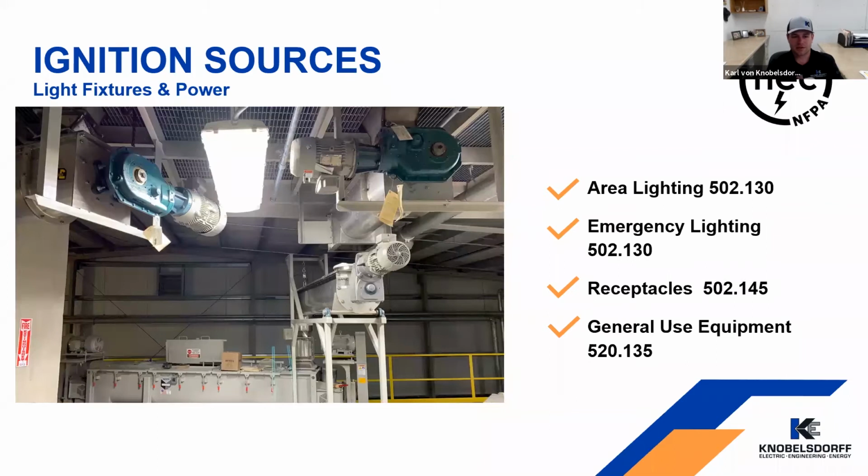So we see that a lot in facilities where they'll do the facility lighting correct, but they miss the emergency lighting. So both of those have to be rated for the area, depending if you're in a Class 2 Div 2 and you could get by with dust type, or if you're in that Class 2 Div 1 and you have to have the dust ignition proof fixtures.